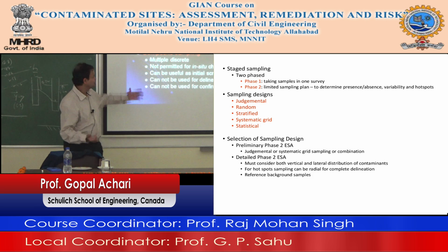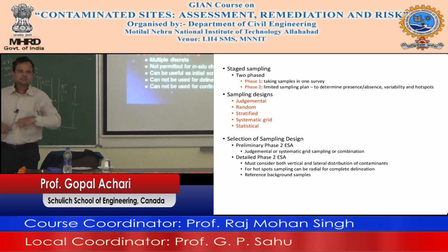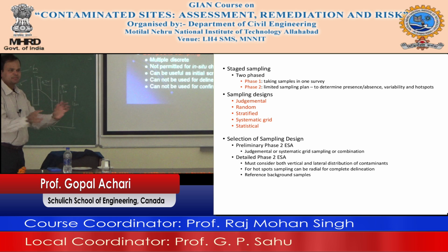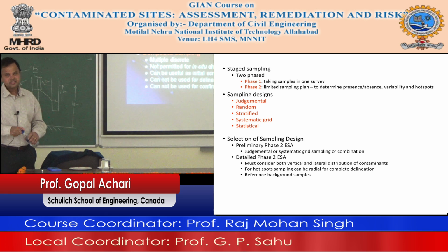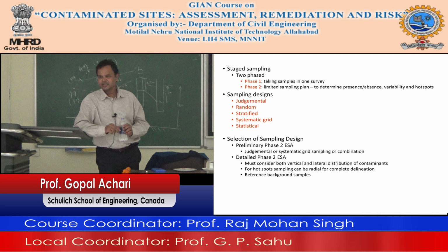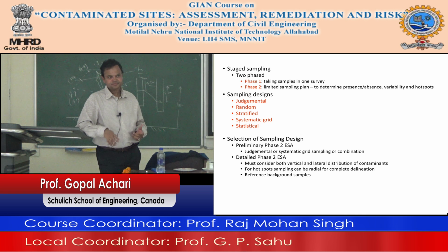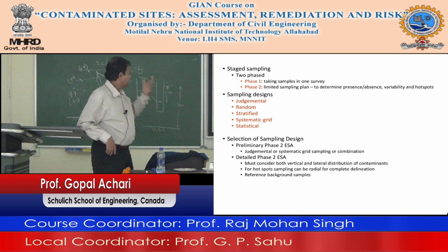You might choose to do what is known as composite sampling. Composite sampling is I take samples, 6 of them in this little quadrant, and I mix them together and send it to a lab. There is an advantage and a disadvantage. The advantage is the cost of analysis is lower because you're only analyzing one sample, even though there are 6 of them. The disadvantage is dilution, or basically homogenization.